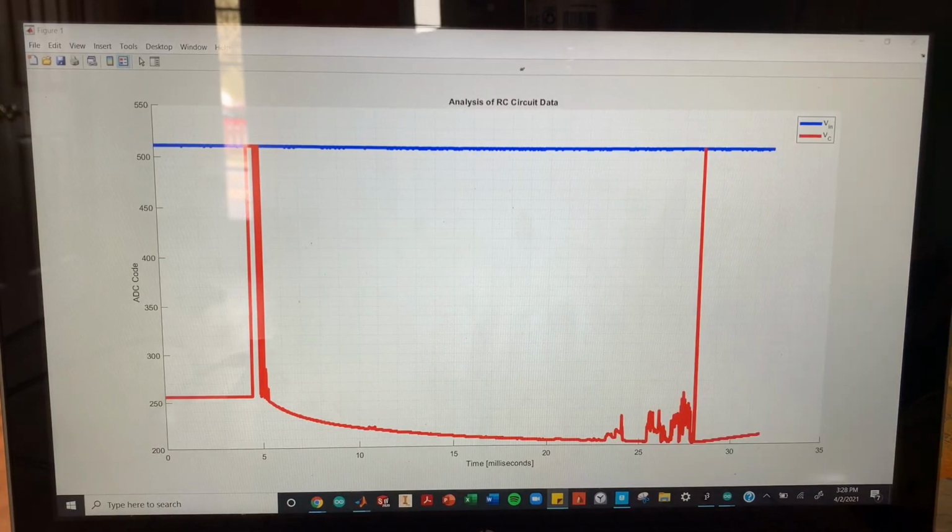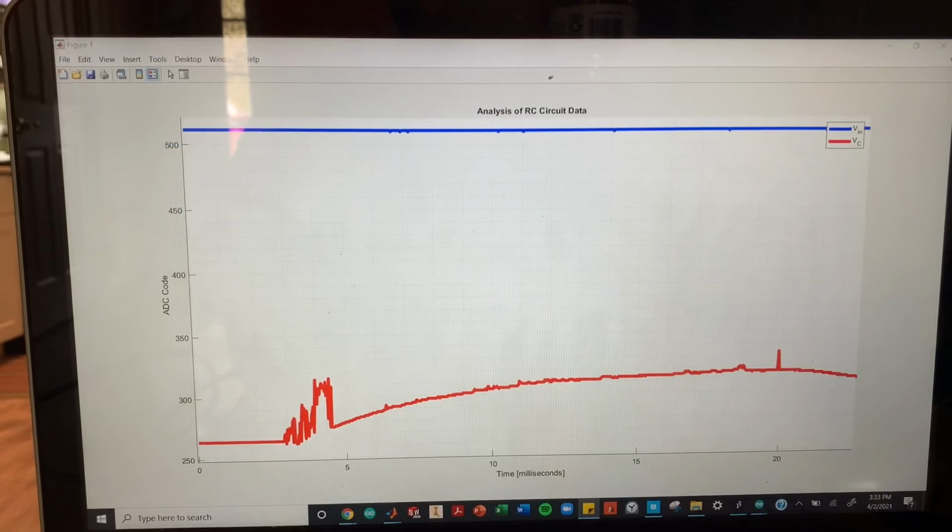So does the thermistor circuit behave as intended? Yes, it does. This is my MATLAB plot when heat is applied to the thermistor. If you ignore the outliers, you can see that my plot does not oscillate the same way that a second-order sensor does. Here is my MATLAB plot for when the cooling ice pack is applied to the thermistor. Ignoring any outliers, you can see that the circuit behaves like a first-order system.